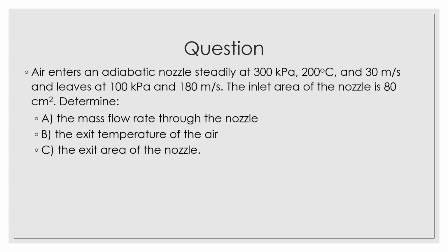While you are getting this question, there are a few important remarks you need to capture. Firstly, air, meaning that we will use the ideal gas equation. Adiabatic, meaning that Q equal to 0. Nozzle is the device that we use for this question. Steadily, meaning that the delta T equal to 0, or no change with time.